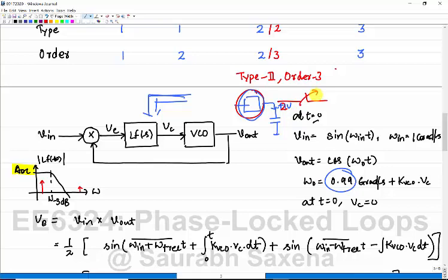Back off means you disconnect yourself. So I charge this particular capacitor to +2 volt, and then this capacitor will hold a charge of 2 volts. This particular system is not going to take that charge and reduce it to 1 volt. That is not going to happen. So if I interfere with the system and give it the control voltage or the phase error which it desires, the system remains stable at that point.